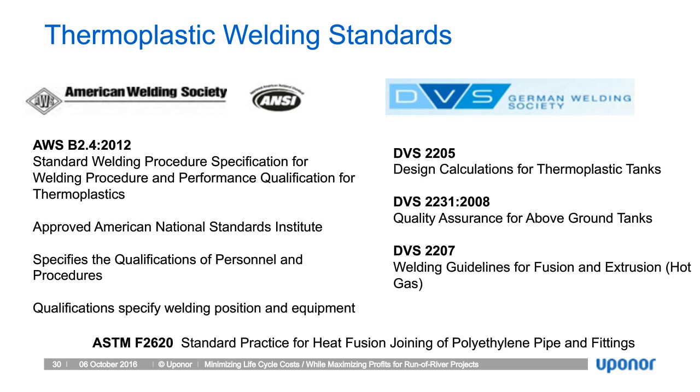Within that standard, it specifies the qualifications of the personnel and the procedures that they have to use, as well as the welding position and the equipment that has to be used in order to properly extrusion weld this material together. We also adhere to the European standards through the German Welding Society.